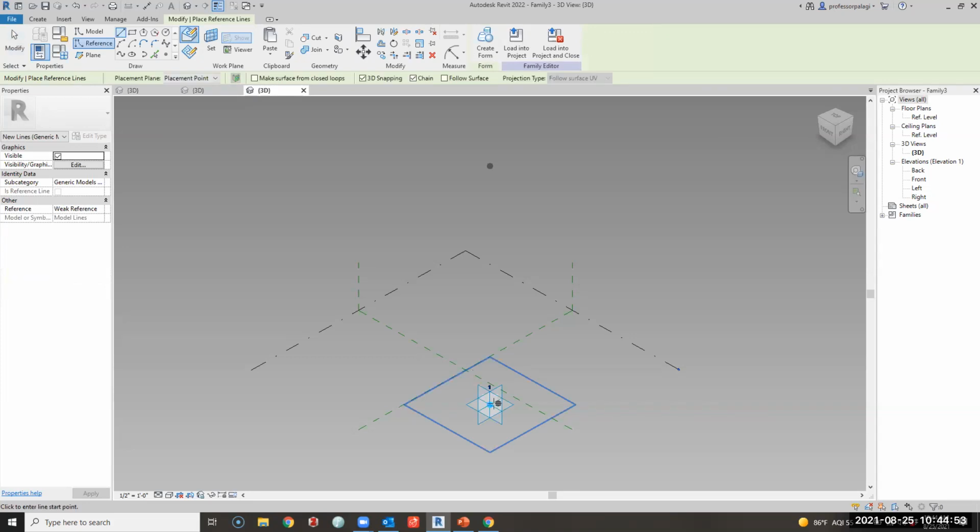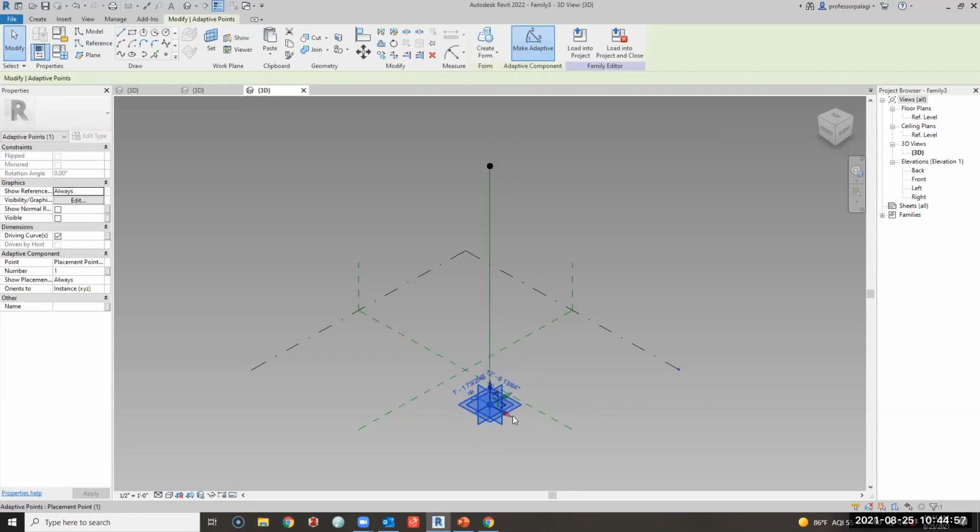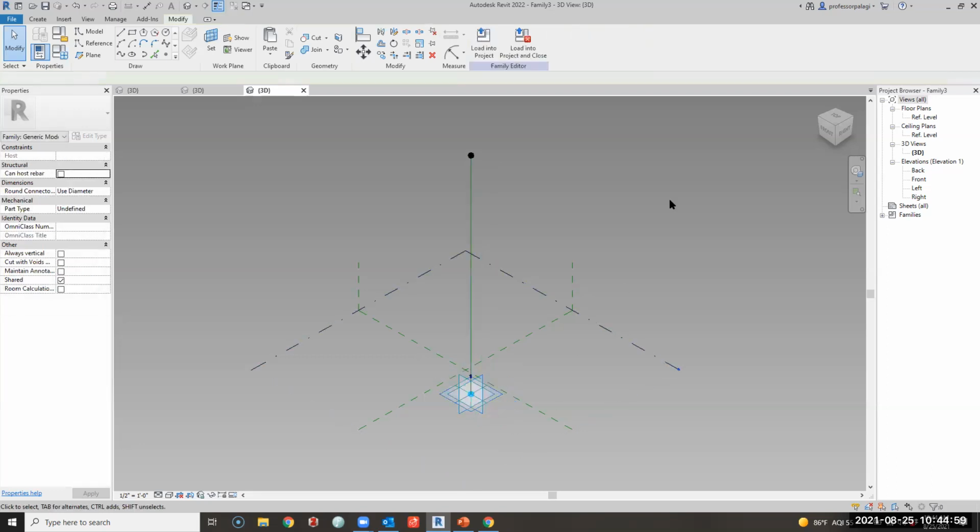Reference line from here to there. Escape, escape. Again, I'm always just moving it to make sure it works. There's nothing worse than working like 2 hours on something and realizing one of the fundamental ones wasn't actually attached to it, and then all the logic isn't there. So the flexing, or just moving it once to make sure it all moves, is what you need to do.